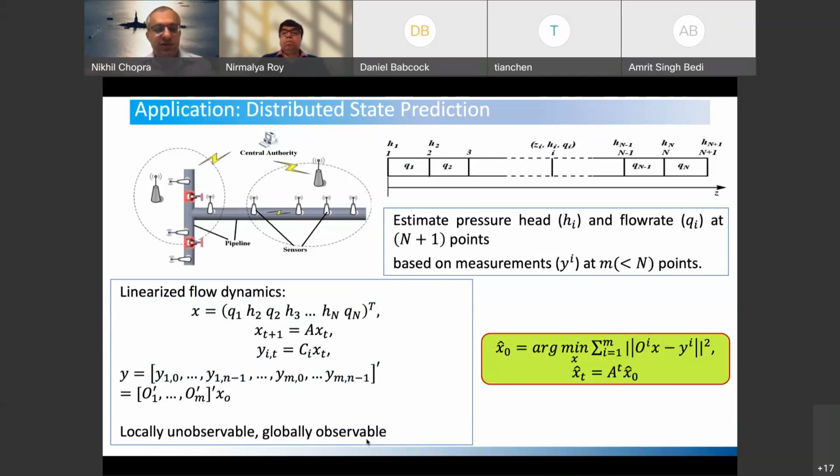And I have a bunch of different sensors, right? It could be a distributed tracking problem, or just some sensor measurements I'm trying to do for something, right? So now, basically in control systems, we have something called the observability matrix, right? The O_i's that you see here are, so to solve this problem, I only need to figure out what the initial value of my state was, and because I know my matrix A, I can compute the future evolution of this.